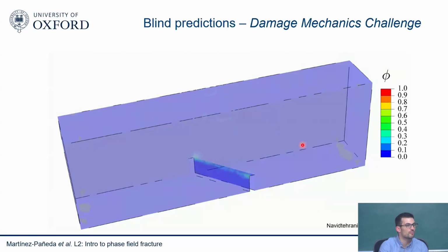So we run a 3D simulation. Again, I'm not doing anything. I'm just running a 3D simulation, plotting phase field equal to 1, contours of phase field. You can see how it starts growing and how the crack propagates. Is the simulation time for this?